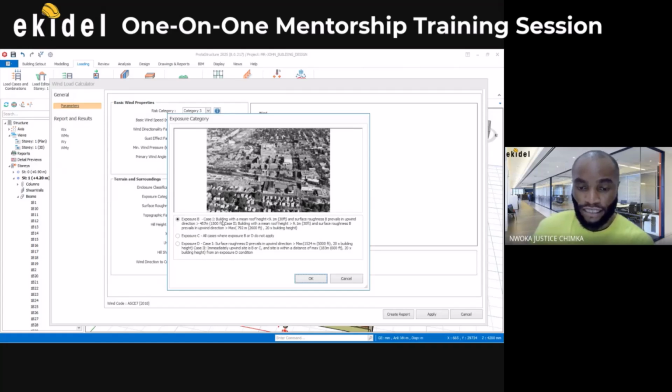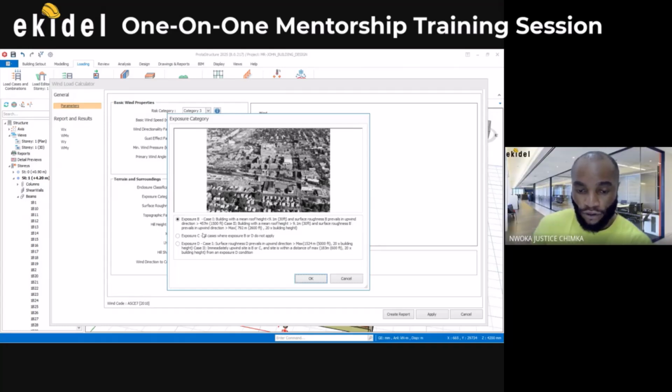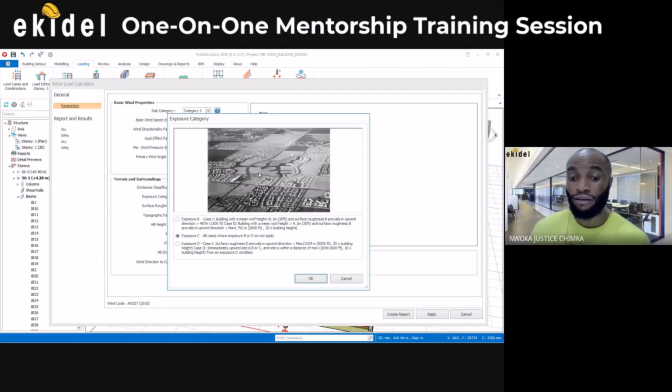Category 1 says building with mean roof height less than 9.1 meters and so on. Then exposure class C is all cases except B and D. So in this case, I can choose category C. You can see the picture of it, almost like a flat land that has buildings not close to each other, spaced out.